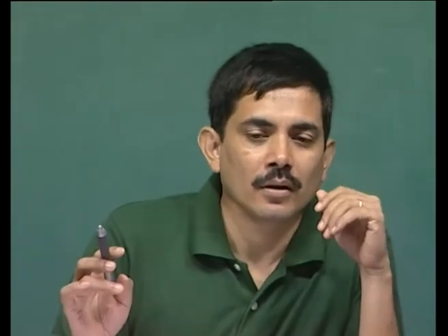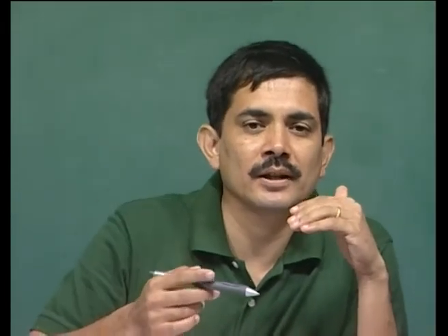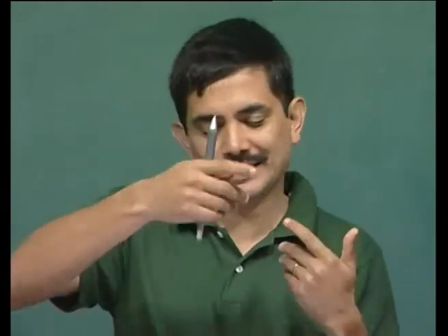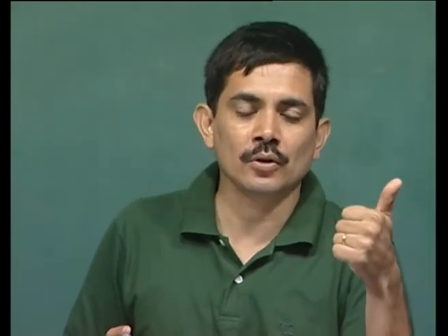Where do you use P controllers? You use P controllers where you really do not care about offset. A very common example is level. In a tank which is just a surge drum, you really do not care whether the level is 50%, 55% or 45% or 60% or 40%, as long as the level is between 25 and 75%, you are okay. So, for this type of a system where the level is allowed to float in a range, offset is acceptable. Because offset is acceptable, the simplest controller that will give you reasonable control performance is a P controller. Simplest is best, therefore, level is typically controlled using P controllers.